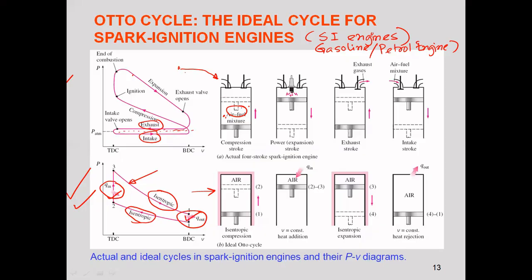But during that time, the piston again moves further downward towards BDC. Therefore, further suction is created, and further air from outside is coming, and this continues. That means as if there is a vacuum always there, and there is a flow always there due to that vacuum. But that vacuum is never fulfilled, never neutralized or normalized by the outside pressure, because throughout the process the piston continuously moves downward. So you have to understand that the subatmospheric pressure always remains during the suction or intake process. A similar thing happens for the exhaust.